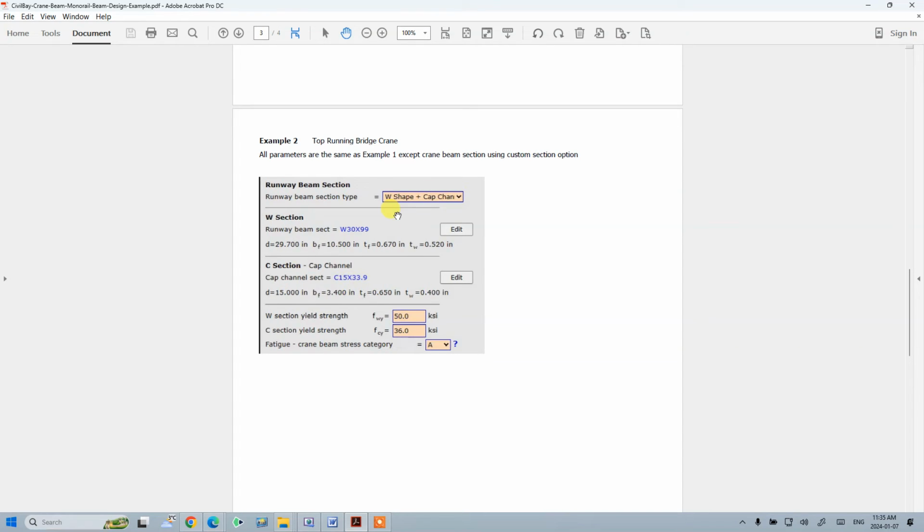I'll just show you an example, you can do the built-up sections for crane one; it will be a built-up girder. Because many times for heavy cranes, the library I-shape doesn't work. Chances are you are going to use a built-up section, which is not from the library. Okay, so we use this library section as an example. We use the built-up to make it. Okay, the ratio will be close. I think it's 0.94, right?